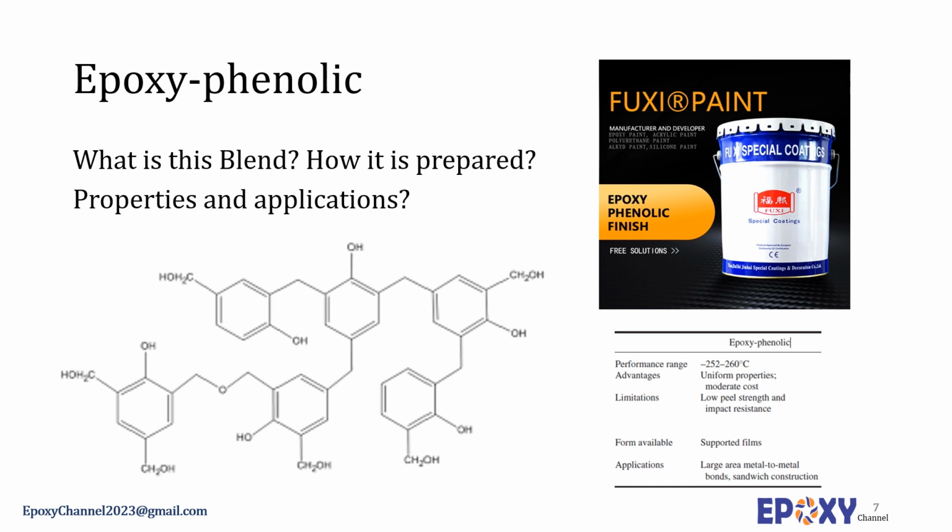Phenolics are compatible with epoxy resins and will react through the phenolic hydroxyl group. The amount of phenolic resin used is generally much greater than that required for crosslinking with epoxy. The epoxy imparts toughness and the phenolic increases the heat resistance. In these systems, the excellent thermal stability of the phenolic resin is coupled with the valuable adhesion properties of epoxies.